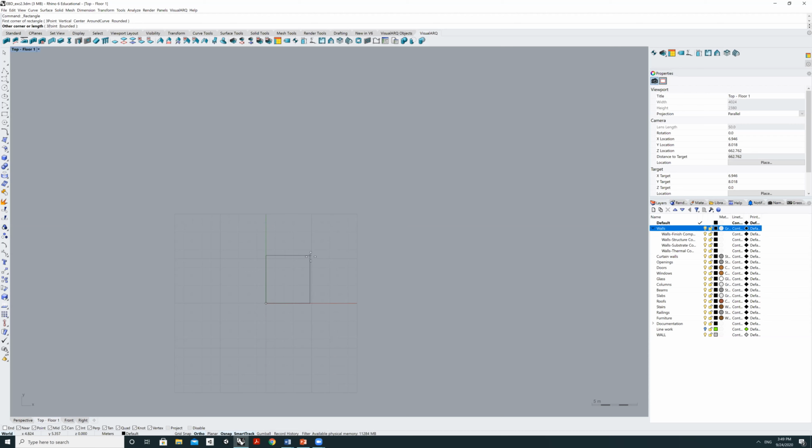So as we've discussed in the last class, office spaces have this 1.35 over 1.35 grid. And if you look at floor plans, we basically see that what we have is 8.1 times 8.1 grids that are this multiplication of the 1.35 measure. So what I'm going to have now is 8.1, right? This is what I'm inputting, times 8.1.